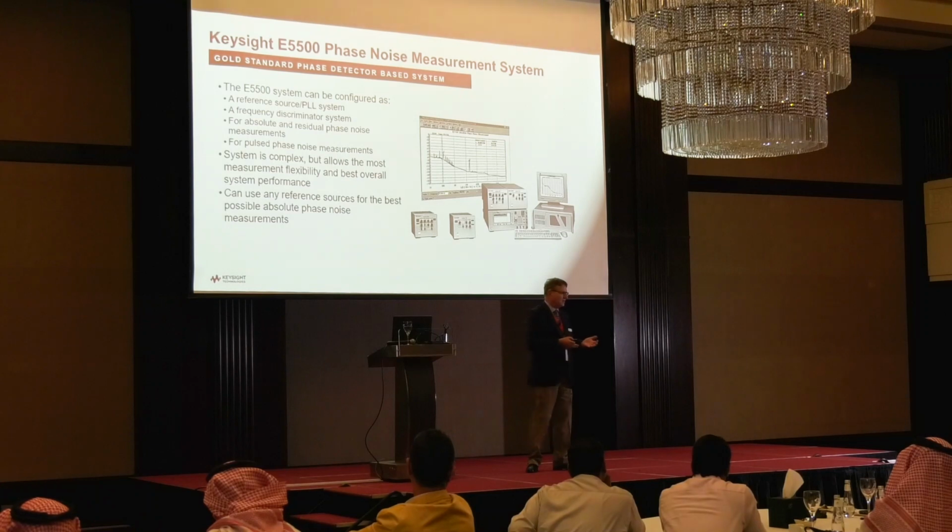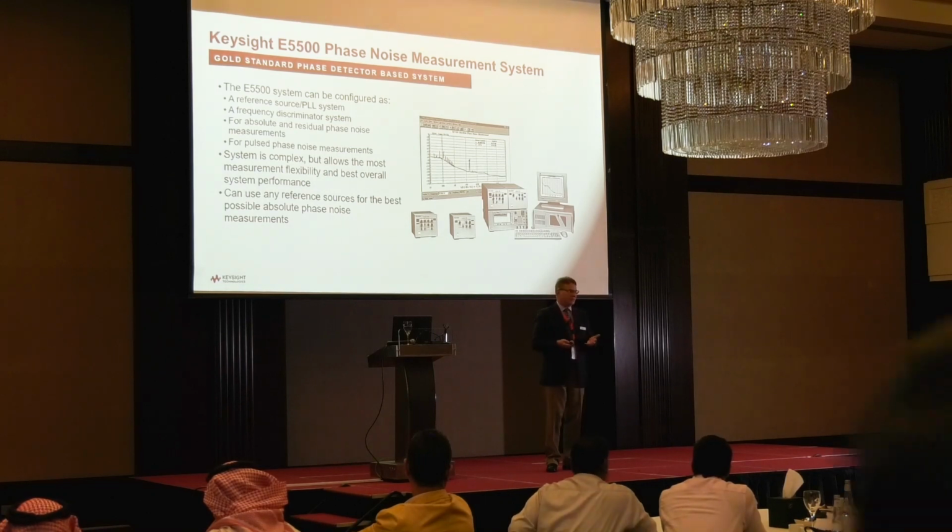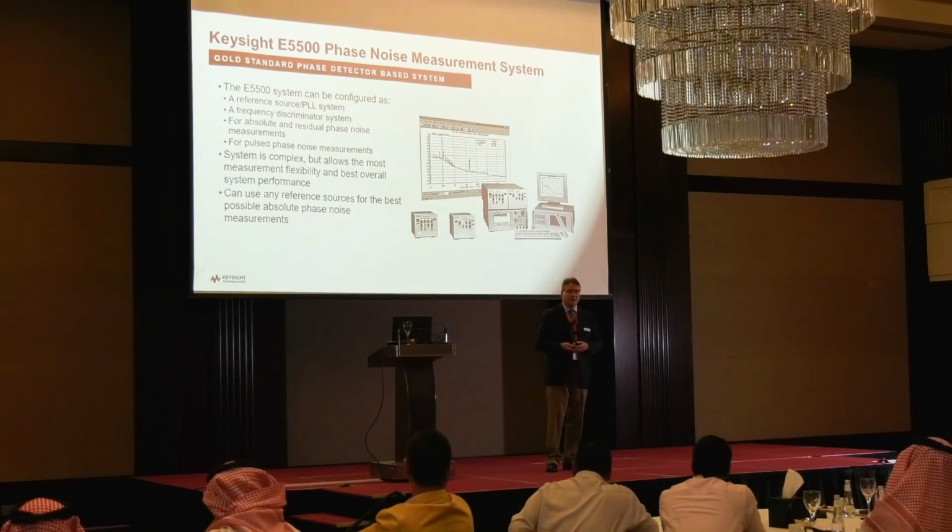So if you have a passive device or an amplifier you want to measure, we can do that with this system, the E5500. And most radar labs will have at least one of these if the designers are trying to characterize very, very low level phase noise, especially under pulsed conditions.